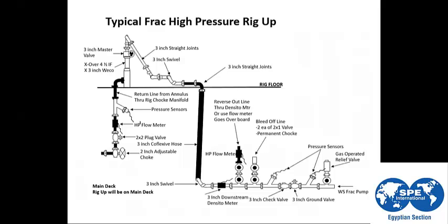This is the connection of the flow line of the actual fracturing job. Here we have the frac gate valve. This is a gate valve with control. This is the first controlling valve at the frac string. Also, we connect through treating iron, 3-inch treating iron, to this valve.